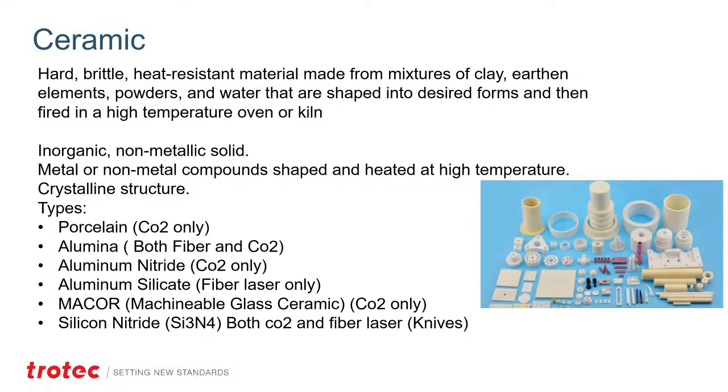And so they're used for heat shields. They're used for particulate shields. They're used for products that are going to be sensitive to some of these harsh environments, mainly heat. Well, the nice thing about lasers is that there is no actual temperature of a laser, especially a CO2 laser. The temperature of the laser is the vaporization point of the material that the laser is hitting. So the benefit of that is we can exceed the temperature needed to melt the ceramics to produce contrast. So we now have contrast marks on ceramics that are designed to go into ovens at thousands of degrees. And that is the great thing about lasers and ceramics.